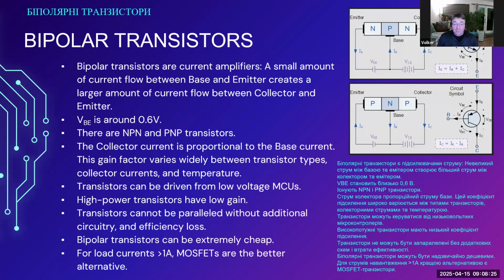The transistor that is best will have the higher gain than the other transistors. It will start conducting more current. If it starts conducting more current amongst the set of transistors, it will get hotter. If it gets hotter, the gain increases. It will start conducting more current, and so on until it burns out.